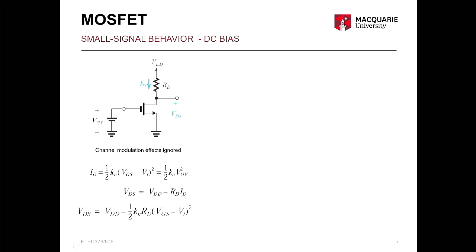So let's look at just the DC bias. We have a DC voltage between the gate and the source, and another DC voltage between the drain and the source, VDS, which we call VDD. So the same ID equation holds, but this is the DC current. That is a constant DC current that flows, and that current and that VDS voltage sets the Q point.